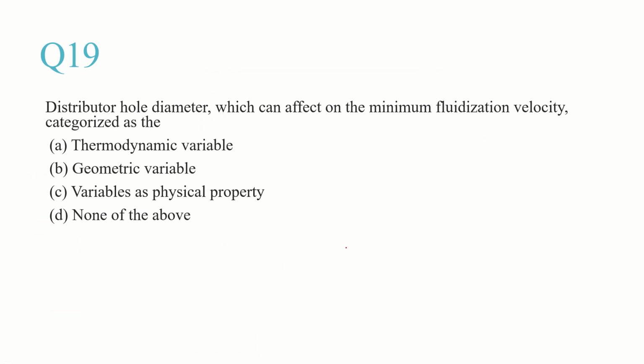When we are passing the fluid inside the bed, we would not be passing it directly. We would be having distributor plates of different designs, and the distributor hole diameter, since it is based on the geometry of the bed, is known as a geometric variable which can affect the minimum fluidization velocity. It is not a thermodynamic variable or a physical property.